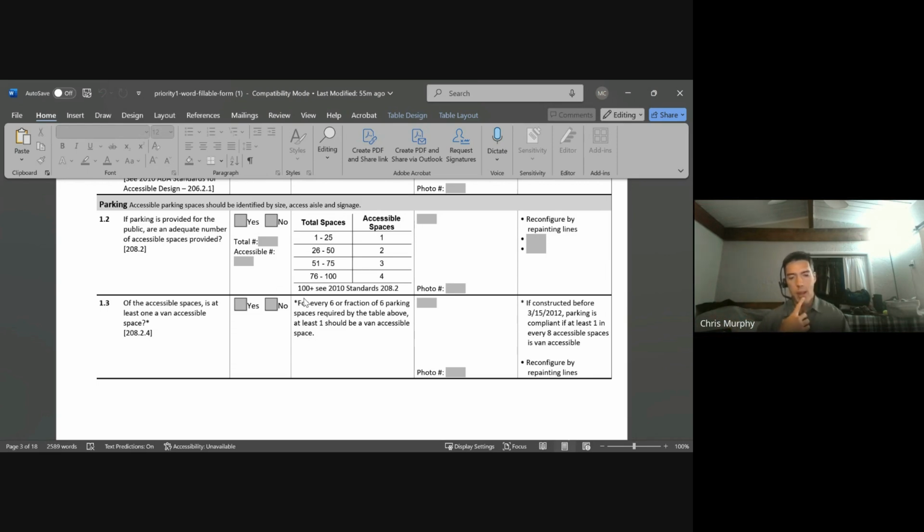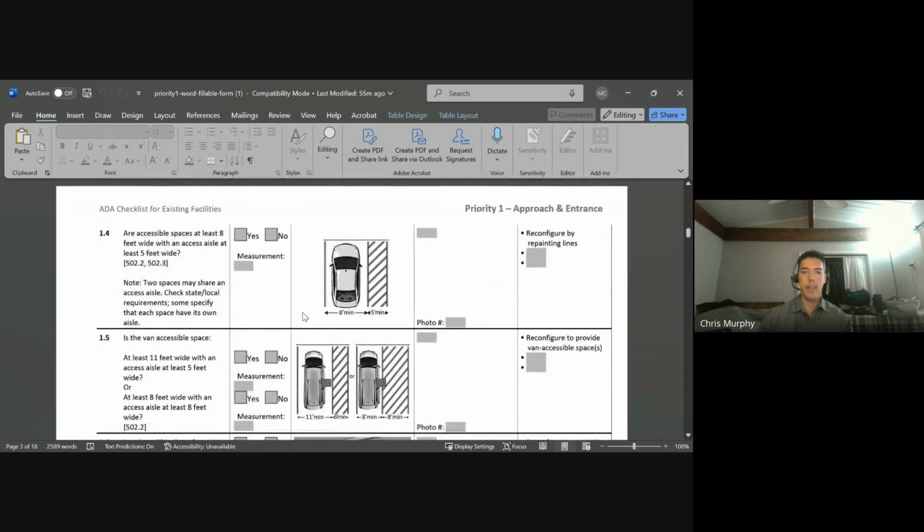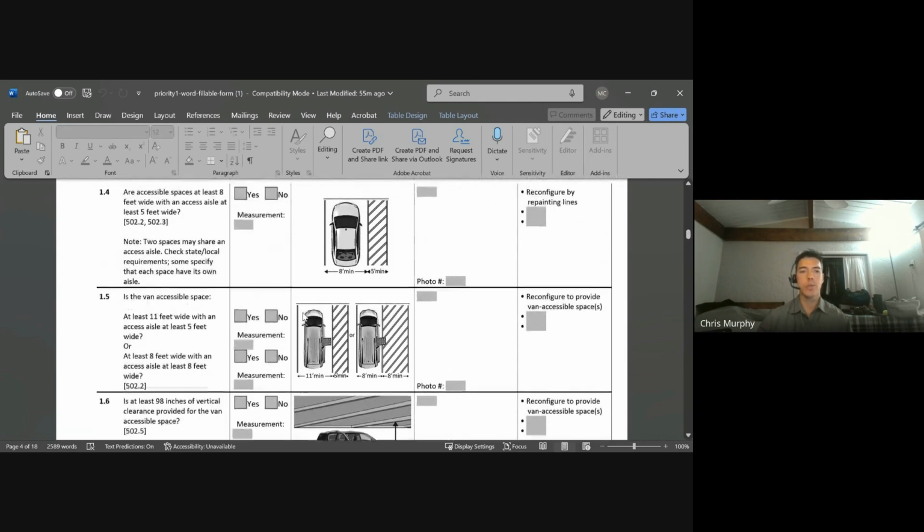If they are required by the ADA, they need to be the traditional ISA. If they're not required by the ADA, the ADA doesn't prohibit it. One thing to understand there is that the painted marking on the ground is not required by the ADA. That's typically required by building code. So you'll have to figure out what their requirements are, but it's not an ADA issue.